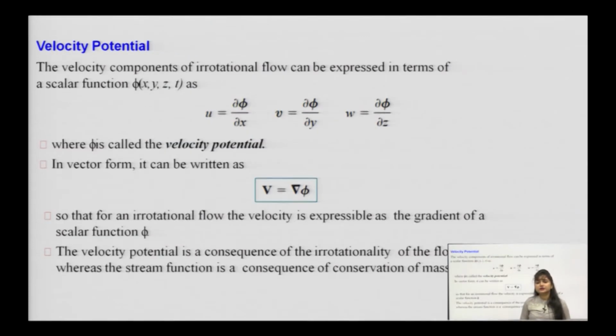Now we will come to the velocity potential function after covering the stream function. The stream function can be summarized in 2-3 major points we can recall: it is applicable for 2-dimensional flow, and it is a single variable, that is psi. It replaces the 2 velocity vectors u and v in the corresponding directions x and y, and with the help of this psi we can draw the curves of constant psi, or streamlines, of variable flow within the flow field.